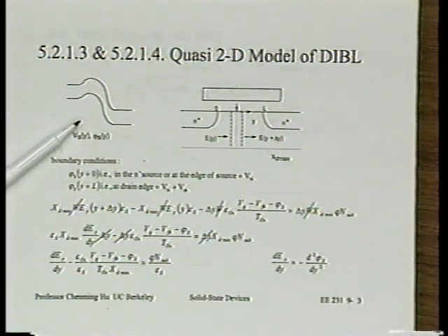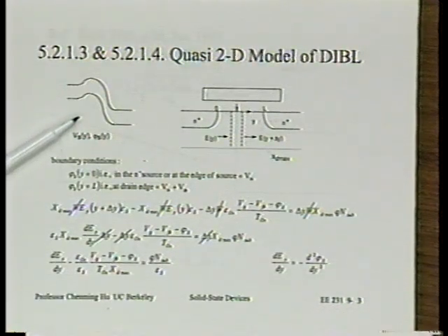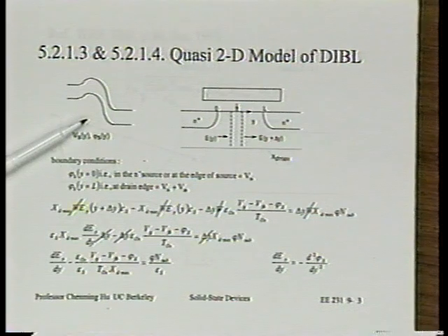You know, actually, perhaps even before we get into this mathematics, which is a little bit messy, let me emphasize the picture I show you. That is using the energy band diagram to understand short channel effect. That actually is the first and foremost thing I'd like you to take from this course. The charge sharing model does not even invoke the concept of this energy band diagram. It does not require you to think that the change in VT is a result of a lowering of the barrier. And I think that is really not good.